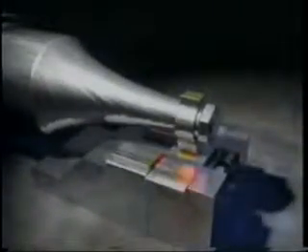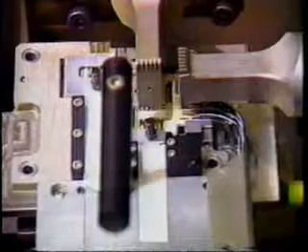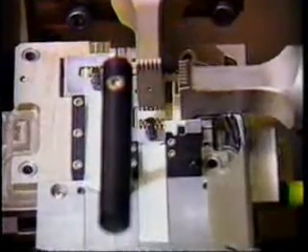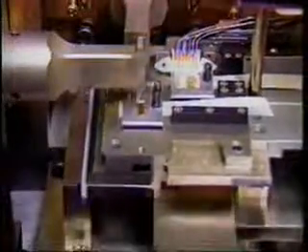Vibratory energy is conducted through one or both tips, which oscillate laterally as a perpendicular force ensures contact of the workpieces. The oscillating action disrupts the interface surface films and permits metal-to-metal contact. This creates plastic deformation at the interface, resulting in a solid metallurgical bond. Under proper conditions, interface temperatures reach only 35 to 50% of the workpiece melting temperature.